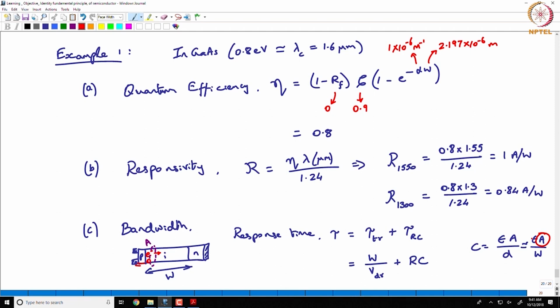It's harder to focus all that light onto that small diameter, so you may take a hit in the responsivity. Not all the photons are being absorbed by a photodiode, right? Let's say 50 microns is your active diameter, if you can't focus all your light to 50 microns, then you lose some photons, they're not even entering that photodiode structure. Okay, so there may be a trade-off in the responsivity.